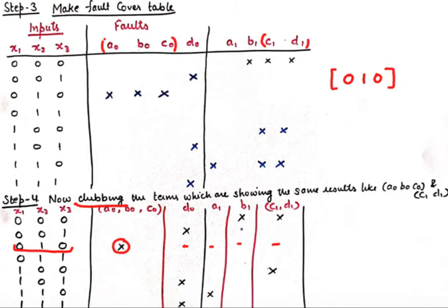Alright. Similarly, you can see in this entire column only B is present, because in this column A, B, C stuck at 0 was present, here B is, and similarly here. A stuck at 1 can cause a problem for the 1, 1, 0 input combination, and that needs to be checked because no other condition covers it.